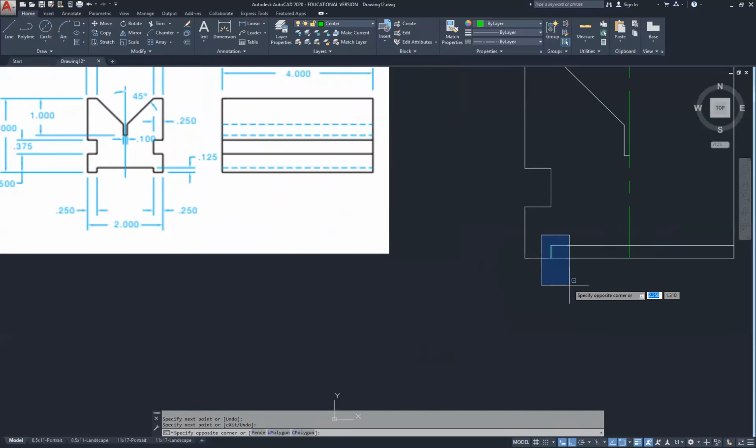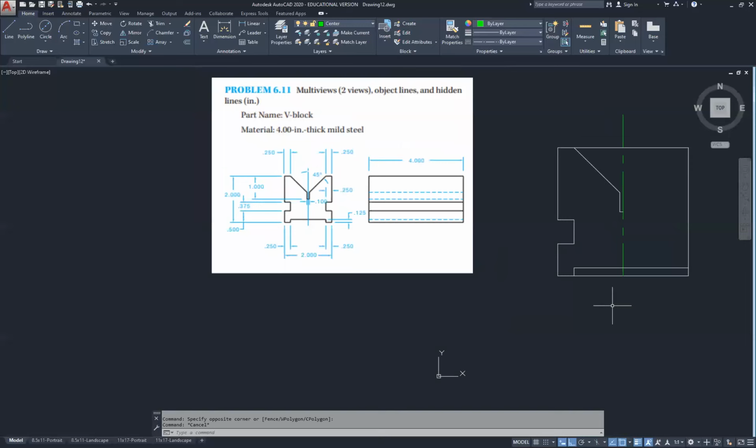I'm going to also highlight that window with a blue highlight window going from left to right. I'm going to change the line type to layer 0. Hit the escape key. As you can see, half the drawing is already done. I'm going to take this to show you the mirror command. In order to do this, we're going to start with the trim command, using that center line as our cutting plane. And I'm going to right click and cut away at the lines I don't need.